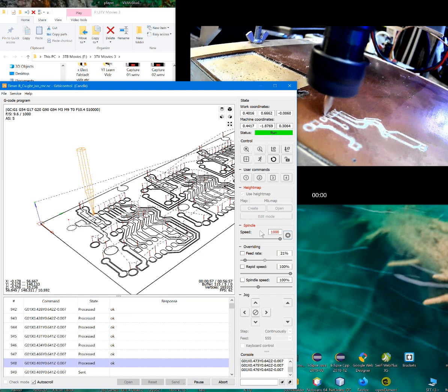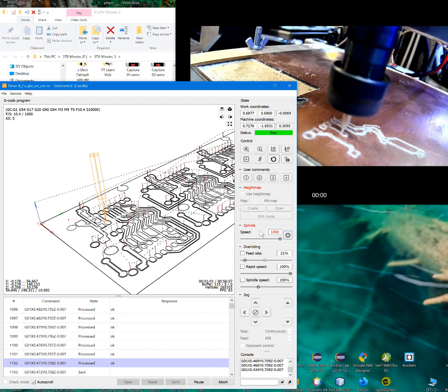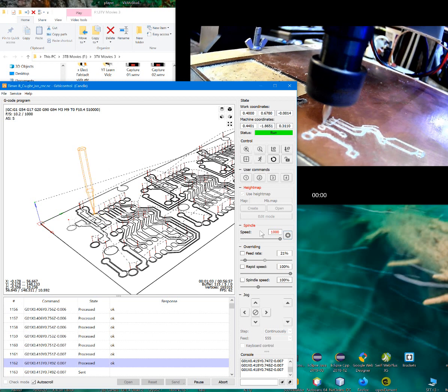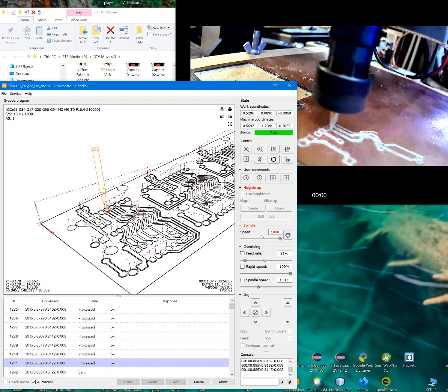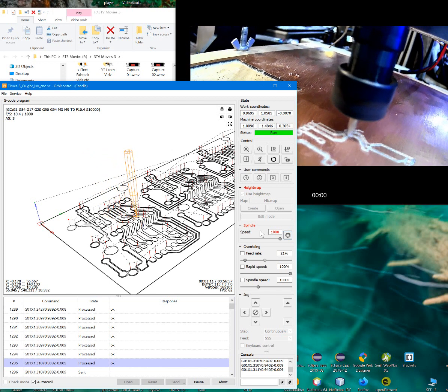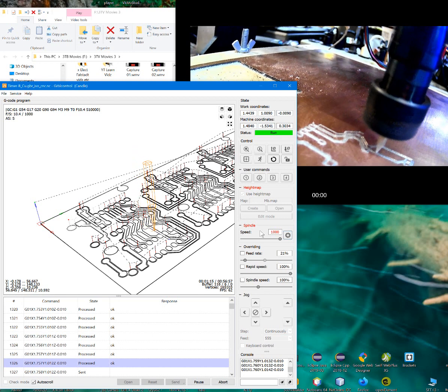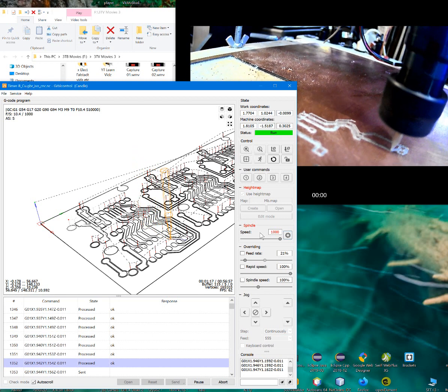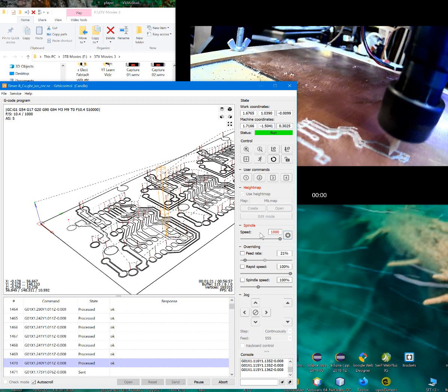Now, I'm sure the more experience you get, the better, but it still depends on the sharpness of your bit. Your bits start to get involved, and you want to slow it down too. With more experience, you could probably get to the point where you have a feel for it, perhaps. But at some point, if you overload your stepper motors, you'll start skipping steps. You really won't like that situation at all.